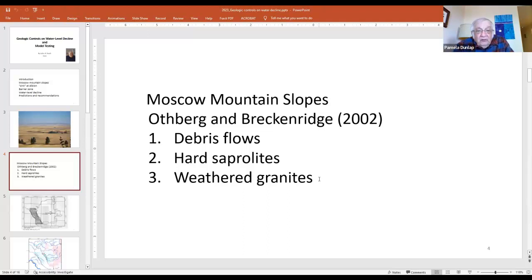For those who don't remember, the problem with detecting the sediments from weathered granites is that the material coming up at the drill site is ground up material, consisting primarily of quartz and clay. And professionals and drillers alike for decades have identified that as granite in almost every one of the well holes. The point is that the work they did helps verify that the subsurface is not granite, that many of the so-called granite wells are really alternations of sediments, saprolites, and weathered granites. And it helps to verify that there are more areas of potential recharge sites all along the slopes, but also up into the mountain highs.